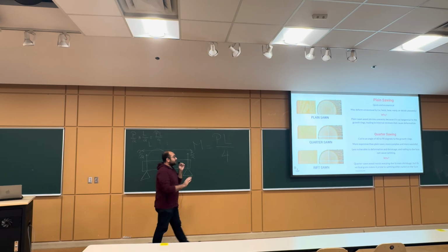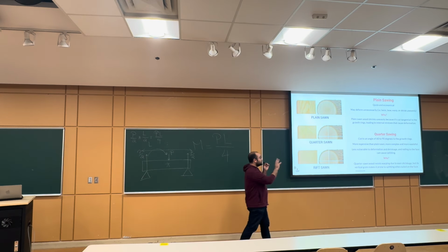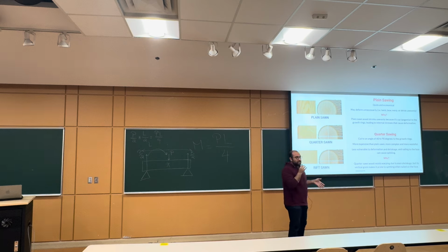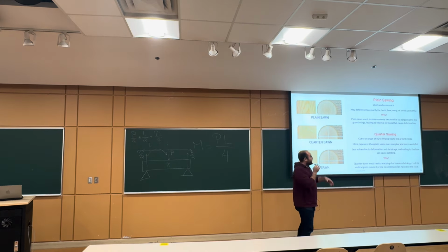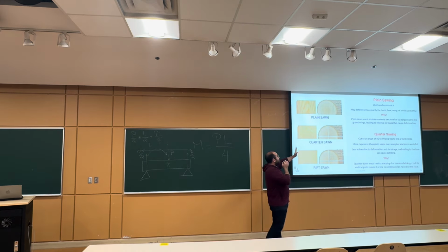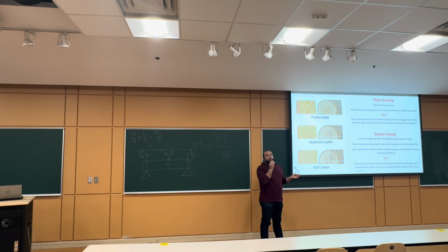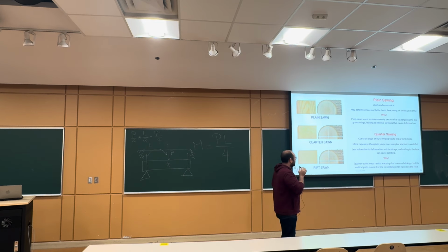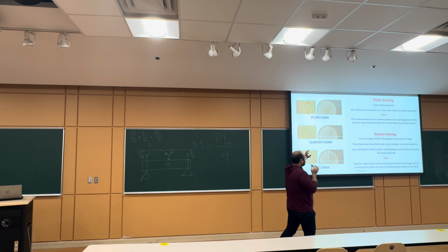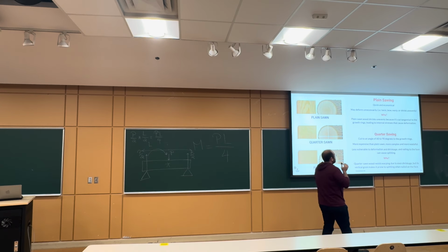So, when it comes to cutting wood, we have two or three strategies or techniques to cut the wood. This is the bigger log that we have here on the right, and how we plan on cutting it, and how good or bad the quality of the material produced from it will be. So, mainly we use either plain sawing or quarter sawing.